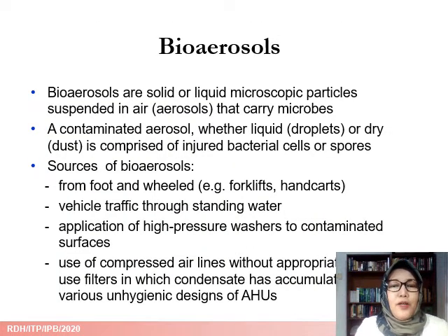So let's talk about bioaerosol. Bioaerosols are solid or liquid microscopic particles suspended in the air that carry microorganisms. A contaminated aerosol, whether liquid or dry, is comprised of injured bacterial cells or spores. Where do these bioaerosols come from? They can come from food, wheeled equipment, vehicle traffic through standing water, application of high-pressure washers to contaminated surfaces, and use of compressed air lines without appropriate use of filters.